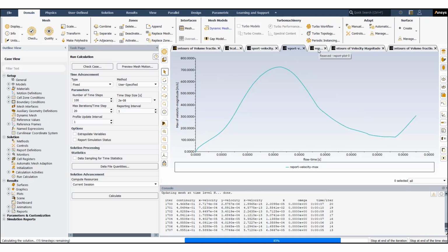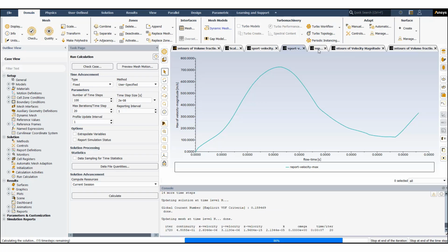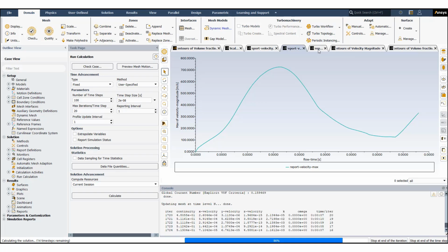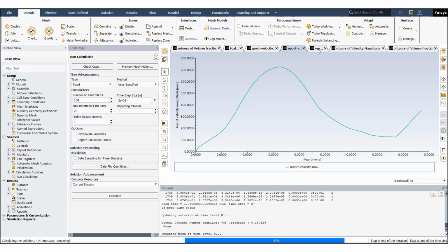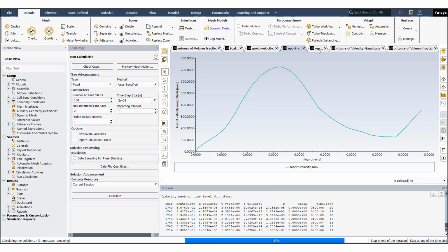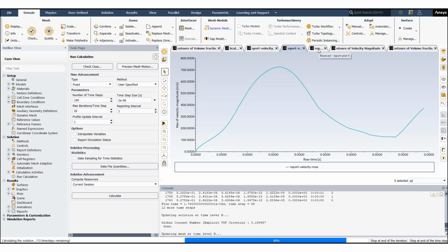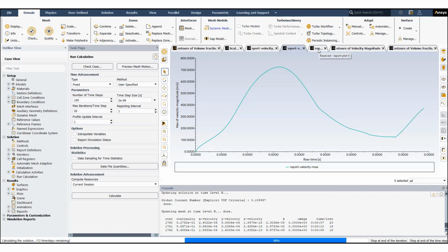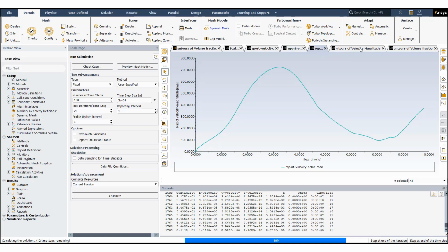So we didn't expect to see such a high velocity, and that's why we have to revisit the material modeling that we are using for water and for air, and also be sure about the mesh, that maybe we need a better mesh resolution compared to the prescribed motion that we have for the moving walls, in terms of the amplitude of the prescribed motion and frequency.